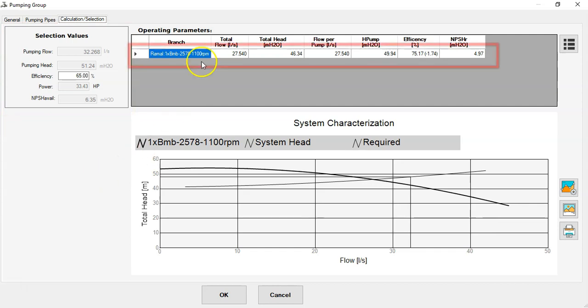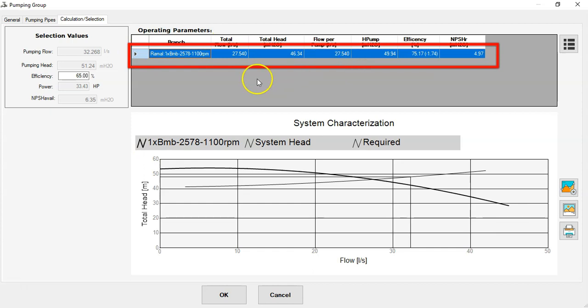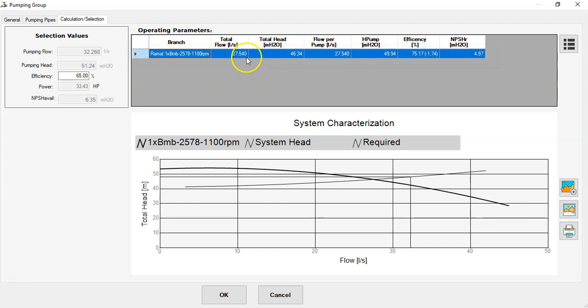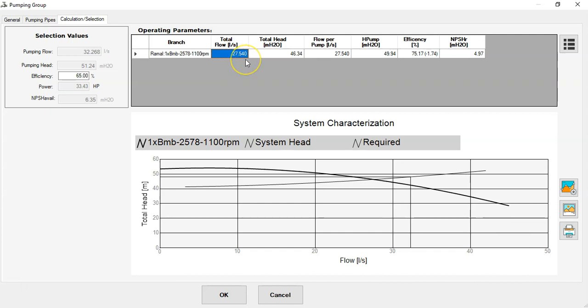On the other hand, we have the actual pumping system's operating information when a pump with the characteristics that we have previously specified through this model is used. And we see that, in the case that in this pumping station operates only one of this equipment, the maximum probable required flow by the system is not reached. Also, it seems that the deviation from the position of the best efficiency point is quite good. Therefore, we could consider studying the results when 2 of these equipment operate in parallel.